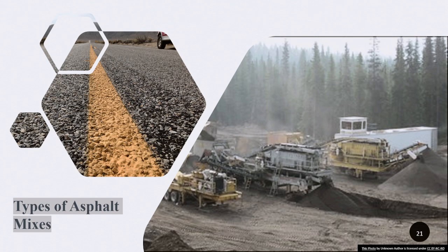In the Superpave, we will talk about how you form your sample using the gyratory compactor and what type of testing has to be done so that you kind of simulate the real life loading that happens from the tires and tire pressure.